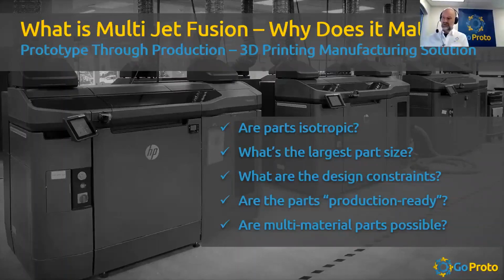So then why this process? Are parts isotropic? That just means, do they perform the same in X and Y direction, the horizontal plane, as well as the vertical plane, or the Z, the build direction? Most 3D printing processes really suffer in strength and material properties in the Z direction because you end up having layers that are stacked on top of one another that don't often fuse completely between them. So the part will fail potentially in the Z direction, not necessarily because the material fails, but because the process of layering creates weaker bonds in the Z direction.